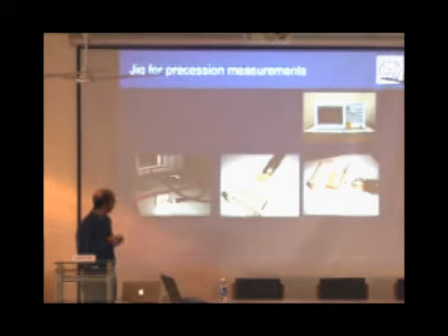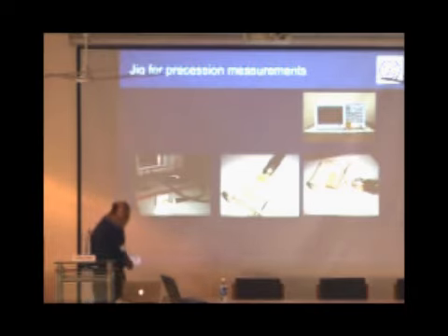So the kind of devices that we make, we connect them to spectrum analyzers. You have to make a RF cage to isolate them. These are the kind of devices that we make. This is a jig which allows us to position the sample right here. What you see here is a copper bow tie antenna to concentrate the field. The field is generated by a RF transmission line which is buried under this substrate, and there is a separate bias line for the bow tie.